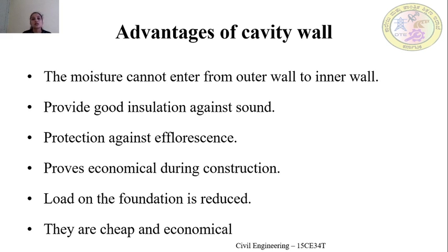So coming to the advantages of the cavity wall, let's see what they are. These are waterproof walls, because since there is a gap between the outer and inner wall, the moisture cannot enter from the outer wall to the inner wall.